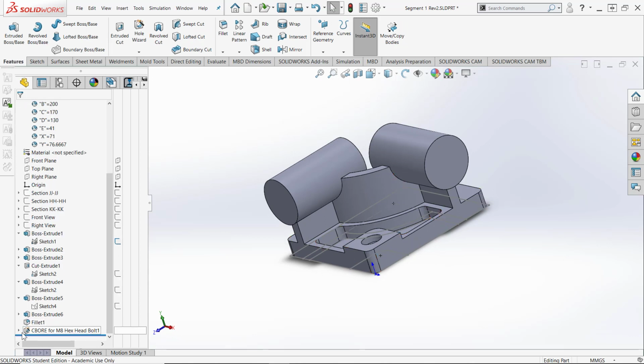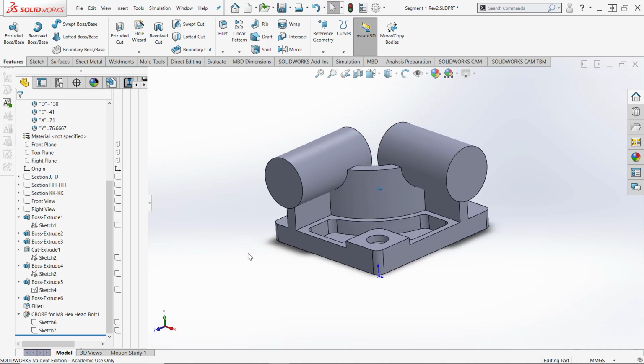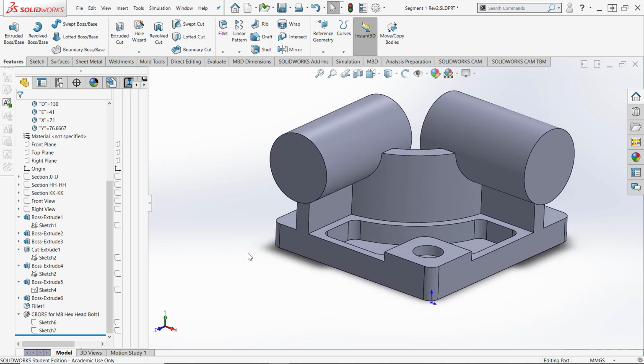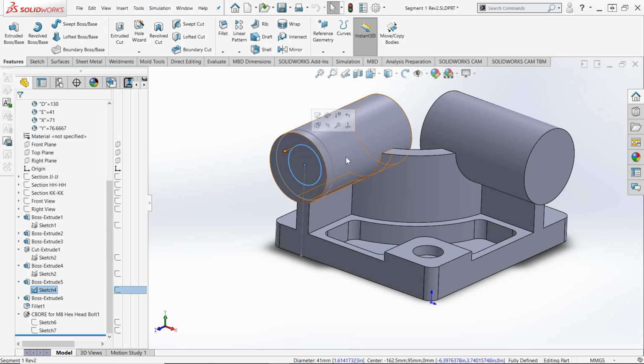If I expand that, check, make sure that those two sketches are fully defined. I don't need to see sketch number 1 anymore, so I'll find sketch number 1 and hide that. And so the last thing I need to do then is put the holes through here and then chamfer those. And it might have been worthwhile to name these sketches so that they would be easy to find, but easy enough to find. So I'm going to do an extrude cut. That's on the plane that's 10 millimeters back inside there, and actually I did a hole. Let's try that again. And you might put these in as a hole.